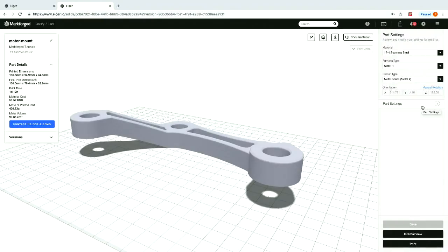Someone asked what the maximum wall thickness is before infill has to start. So on metals, I'm not 100% sure. Is it 800 microns, or maybe it's 1600 microns? I don't know the post-sinter bead width on the Metal X. But we could give you that information. Just feel free to send us that question, and we can reach back out. And then on the composite side, you can vary it, so you can add more walls. I think the maximum thickness on a composite one is 1.6 millimeters.